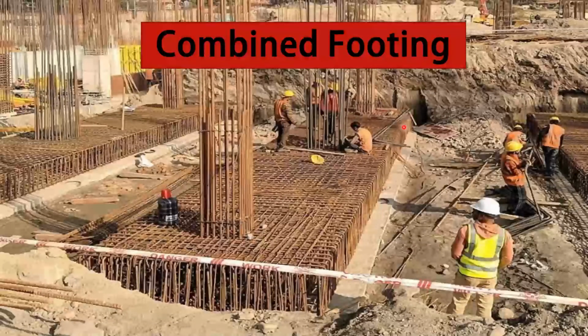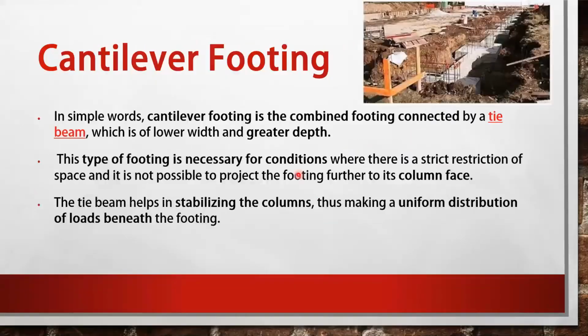So over here we do have the space for the combined footing, but since on the other side you can see the space is not available, that's why we are connecting these two footings with a tie beam, and that's why it is known as cantilever footing. And this tie beam helps in stabilizing the columns, thus making a uniform distribution of loads beneath the footing.